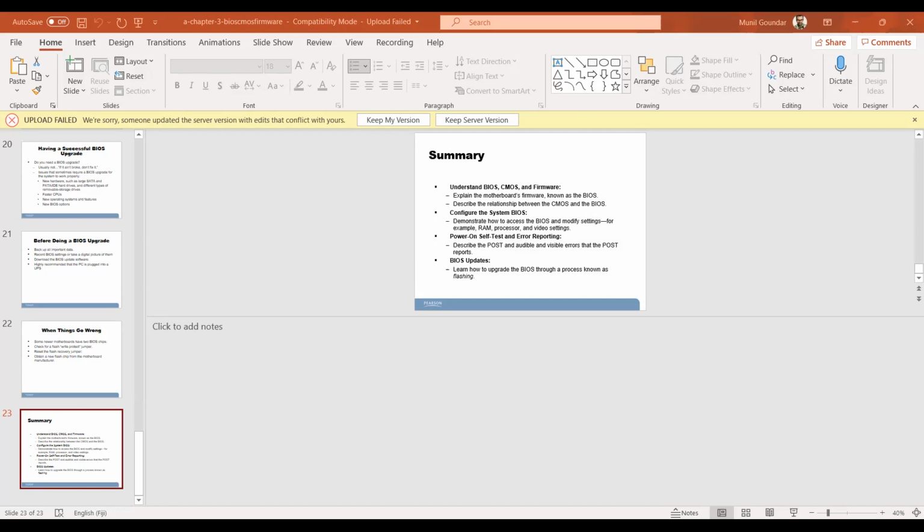Now you would see that in the illustration, a RAM is attempted to be installed. In the first image, the image on the top, you would be able to see that the RAM has not been properly engaged. Try to have a look at this portion, whereby you see that these are still quite above the slot. And if you look at the bottom picture, you will see that the RAM has now been engaged, and the silver chips, or the pins as we normally call them, have been inserted in the slot accurately.